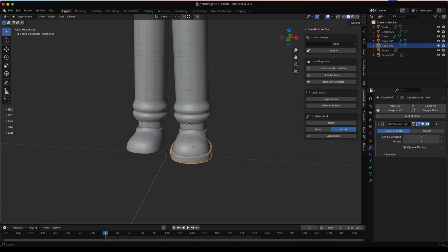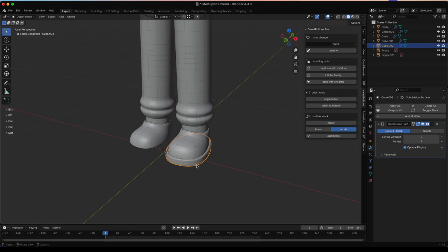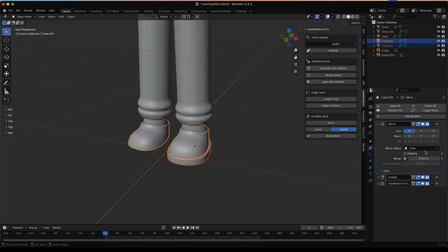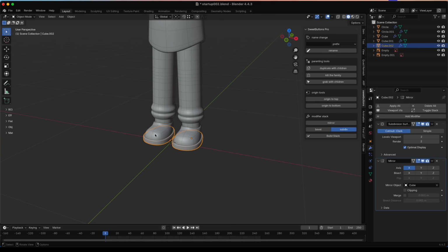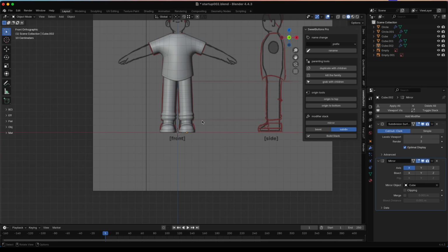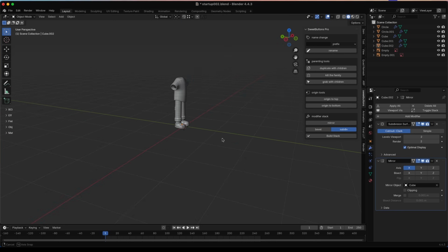And we can select our sole here. I kind of forgot what that part of the shoe was called. We can select our sole and then shift select our shoe. And then under the mirror modifier that we just kind of dialed in the parameters of, let's go ahead and untick merge. We can go down here to the drop down arrow, this little chevron, and we can do copy to selected, and that will just move only that modifier over to that object. So here we go. We have a nice looking base.